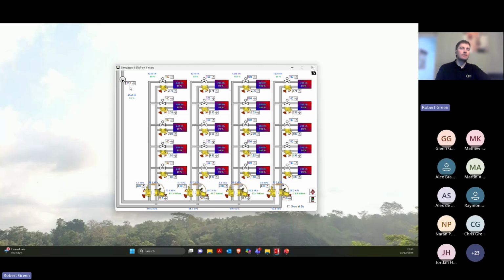And in this example, we've taken 25 kilopascals off a 150 kilopascal pump head. So we've reduced that pump head by around 15% or so. Give or take 15-20% reduction in pumping head. And that's a direct reduction in OPEX there.